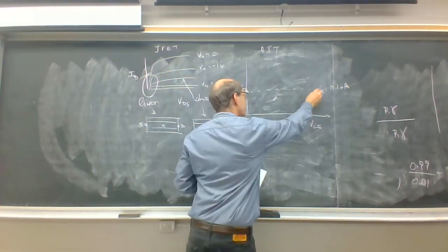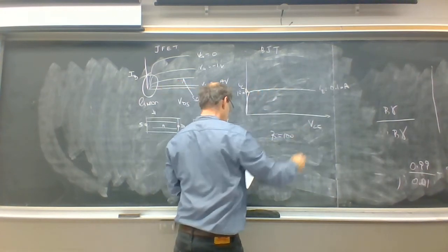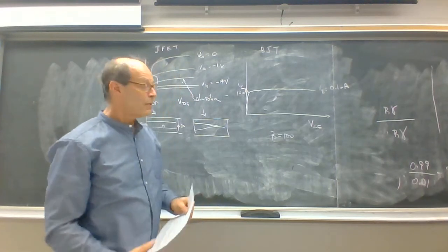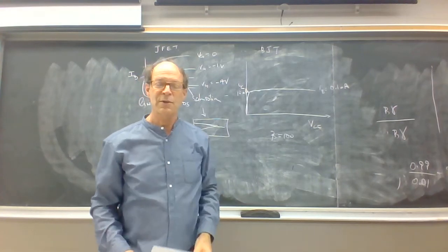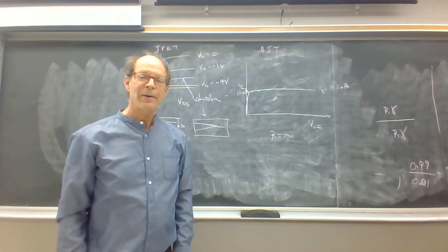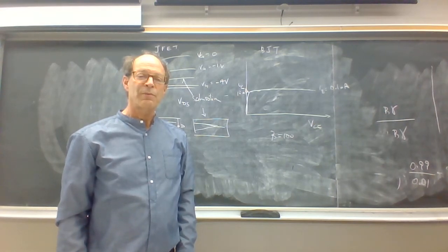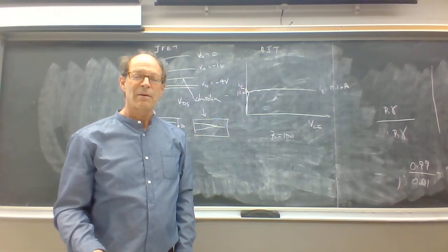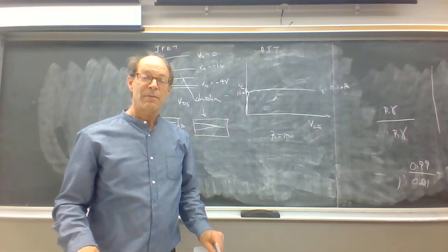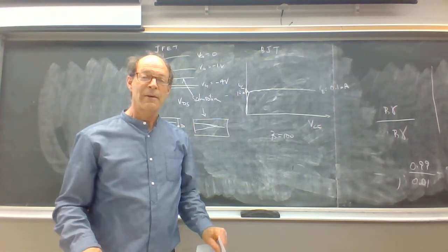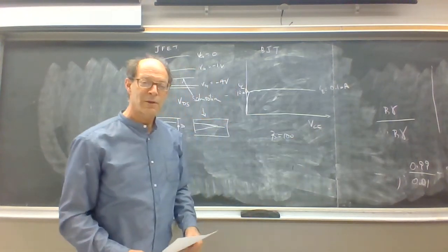So you get this curve here until you reduce the collector emitter voltage to a very small value. So you get a saturation effect in a bipolar junction transistor. And of course, what's going on there is that the base current is what's recombining in the base plus what's being injected into the emitter. And that same situation keeps going regardless of how big the collector emitter voltage is.